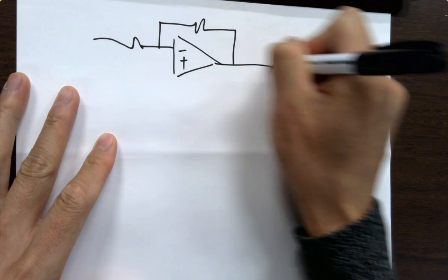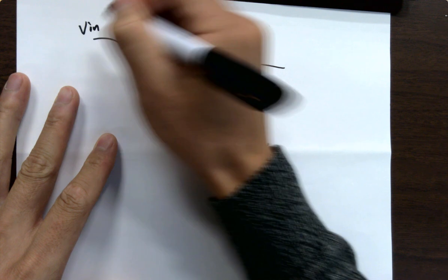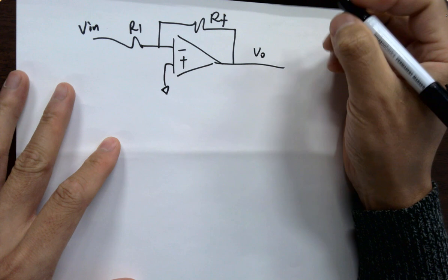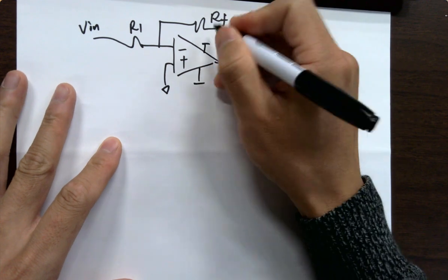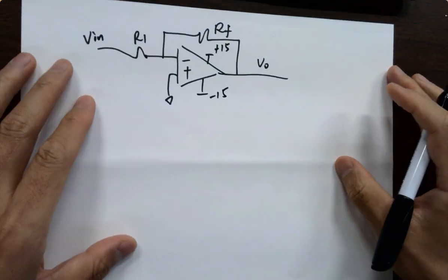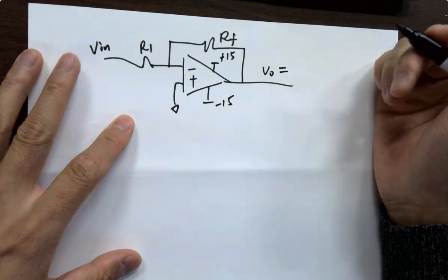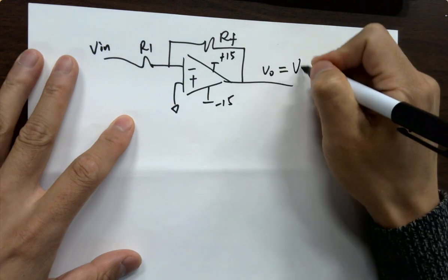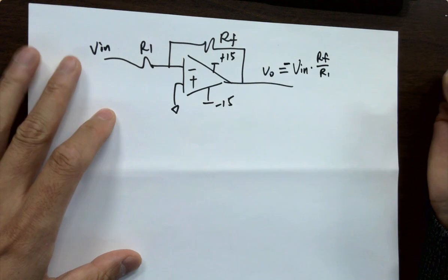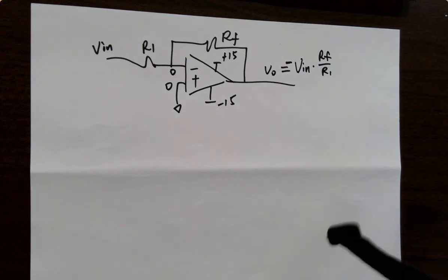Before getting into the details, let's just repeat what we have learned before, by far, and see if we can find out the correct answers. If I power up this op-amp by plus 15 or minus 15, what is VL? Just list the equation. So VL equals what? Minus, because here's 0, here's 0, it's virtually shorted because of the feedback.